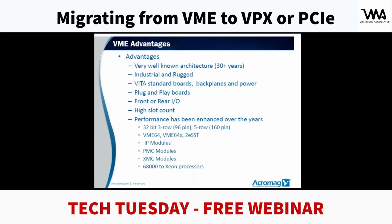VME started with a 32-bit, 3-row, 96-pin connector and migrated to a 5-row, 160-pin connector. Over the years, we introduced VME 64, VME 64X, and 2eSST technologies.